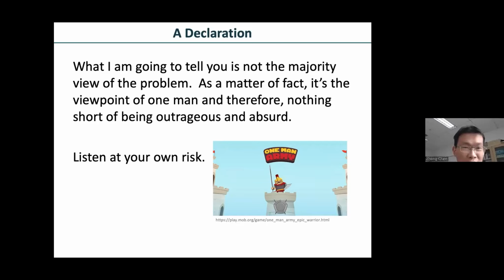Okay. Professor, thank you for the nice talk. According to my understanding, HyChem is based on the assumption of time-scale separation, that pyrolysis is much faster than oxidation. Correct? So I'm wondering whether there are some situations where this time-scale separation doesn't work. Firstly, I'm interested in detonation. You also work on detonation. In the detonation, the temperature and pressure after shock is pretty high. So I'm wondering whether the oxidation is still slow compared to the pyrolysis.